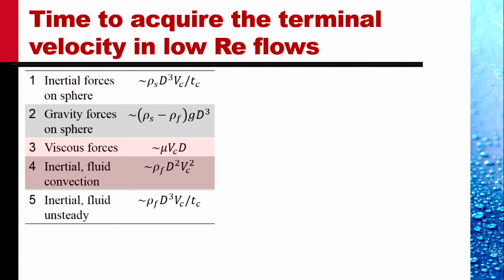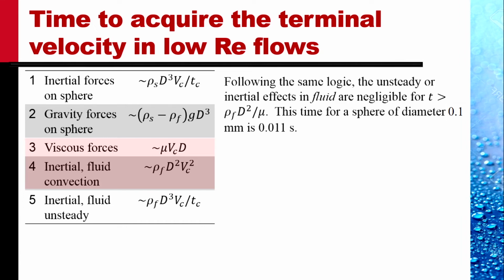Now let's look at when the unsteady inertial forces in the liquid can be neglected. Following the same logic, the unsteady or inertial effects in liquids are negligible for t greater than rho f d squared divided by mu. We can neglect the inertial effects of the fluids.